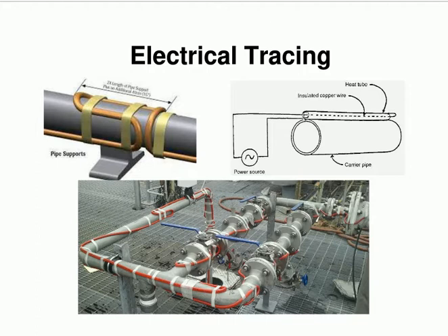Okay, so pretty much the same thing. The only difference is that for one we've got a hot liquid, the other one is electric. The hot liquid, as far as energy is concerned, may possibly be more effective, but for electrical ones, there's no messing about. You just connect it to a power source. You tape the heating wire around the pipe, put some lagging around it, and you've got it. But you don't have to worry about any liquids or heating up liquids, or having a hot water tank where you get the heated liquid from, so you don't have this problem.